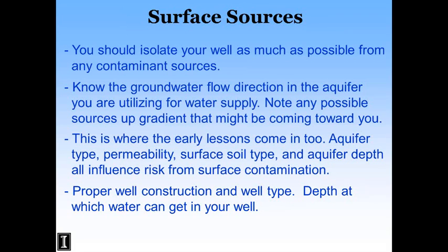It could also be an issue of maybe you're in a rural subdivision, like the picture I just showed a minute ago with the arsenic example. Maybe your well is up gradient of your septic system, but your neighbor that's up gradient of you has both a well and a septic system as well, and so you need to be aware of what your neighbors are doing as well in order to really protect and understand what your risks might be.